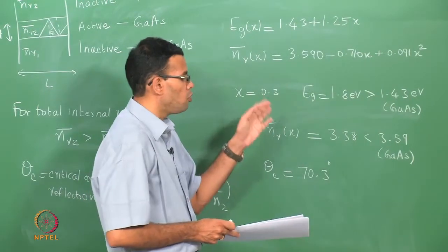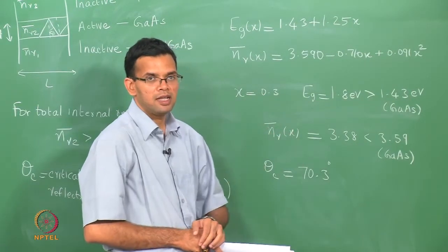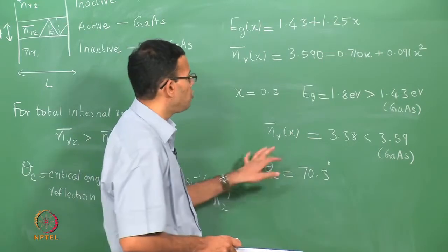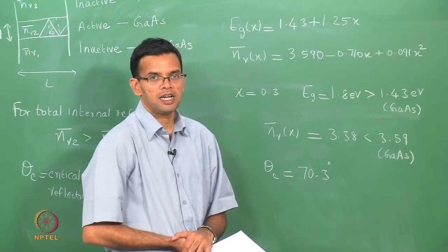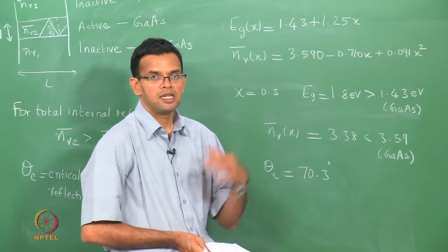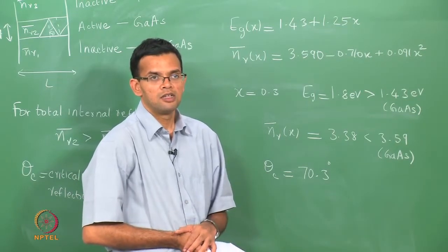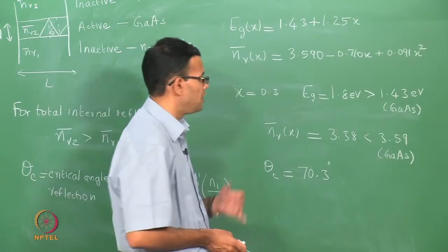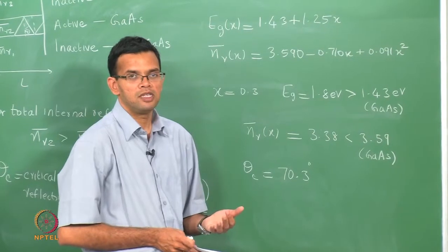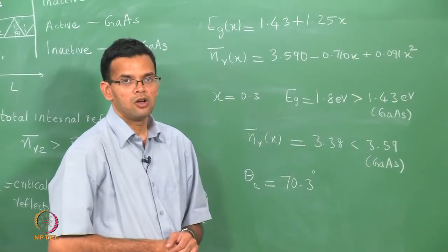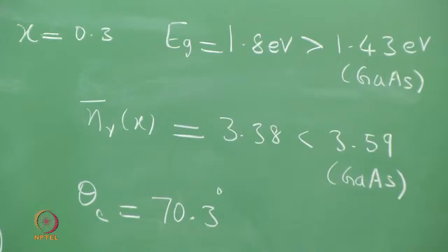So, by using both optical reflectors at the edges and also by waveguiding, so by using a graded structure with different refractive indices, you can basically have lasing action. This action is similar to that of an LED, but in the case of an LED we do not have these optical resonators or these waveguiding structures.